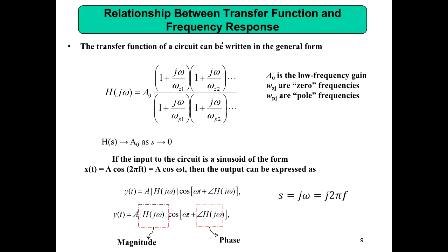Yes, then this is a standard equation. How it is related to our equation is that this is equivalent to our gain, V out by V in, the transfer function. In electronics it is V out by V in, and that is equal to the low frequency gain when frequency tends to 0.